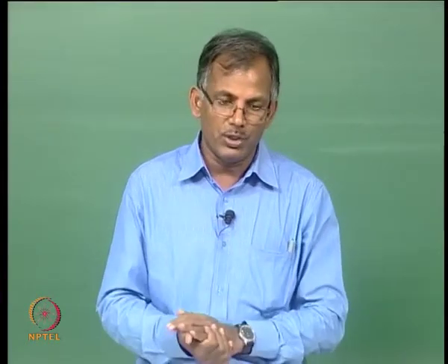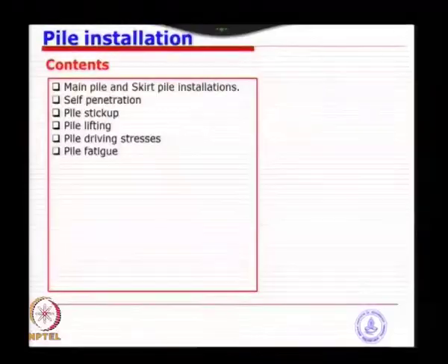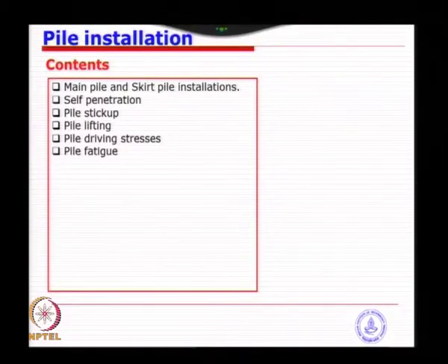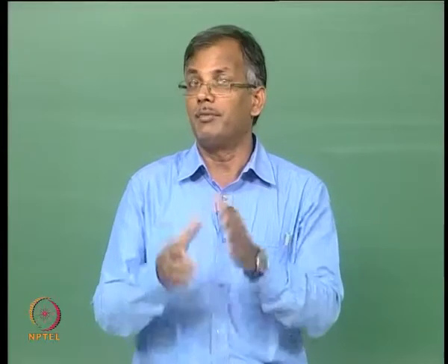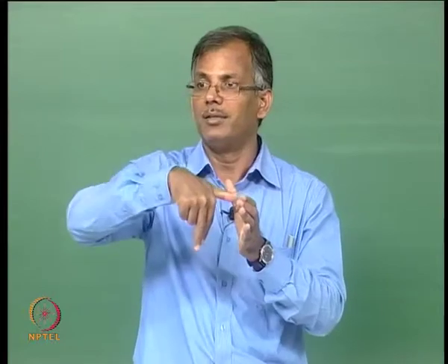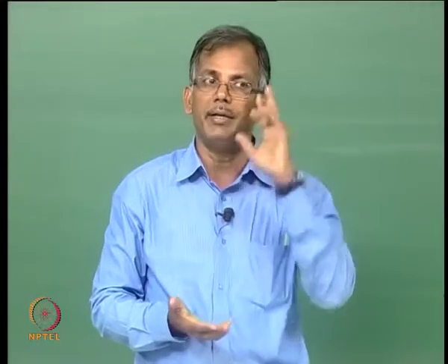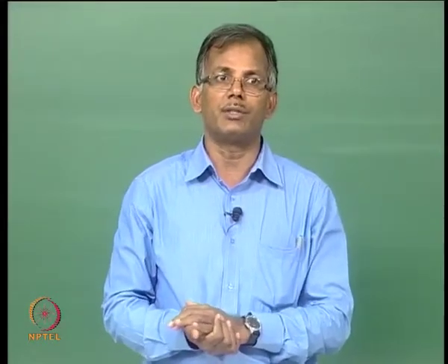So, we are going to look at various aspects of pile installation and associated issues. The first one, let us understand how the piles are installed for both main pile and skirt pile, and then we will look at various other aspects, like when you place a pile into a jacket slot, if it is a main pile you will insert it through the main leg. I think all of you have some idea, we have already discussed it in the introduction.